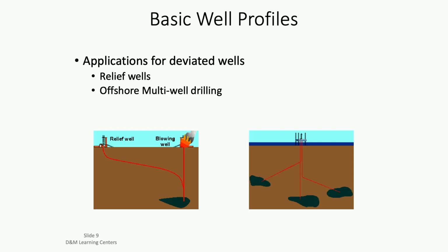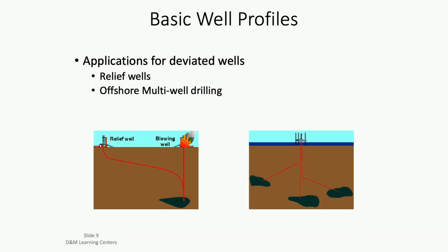There's another example of us hitting where we need to go and then relieving the pressure. A lot of times we'll drill down into these pockets of gas and we'll get kicks of gas, so we have to relieve the gas. We can manage the gas by controlling our mud weight and kind of pushing the gas back down, but sometimes we can't always do that. So we have a relief valve that comes out, and I'm sure if you live around here you have seen them burning the gas off. Even at some of the plants, they get too much gas and have to burn it off. And sometimes when they burn that gas off, they can't control it, so they'll either shut the well in or evacuate everybody off location. Then they get specialists to come in to handle it.